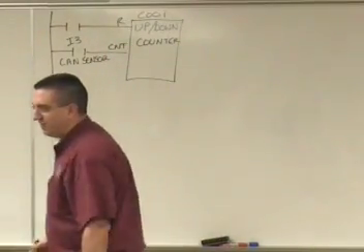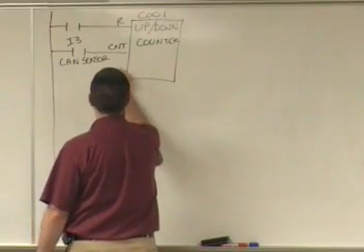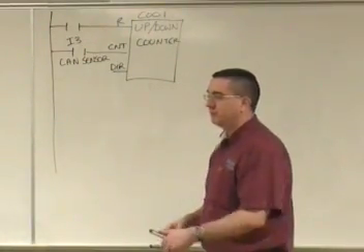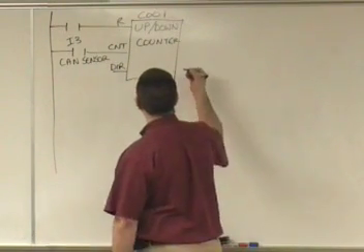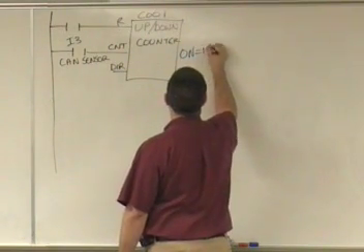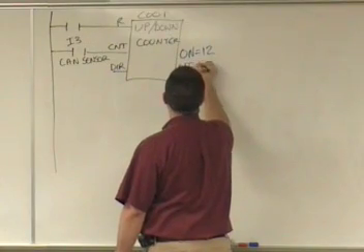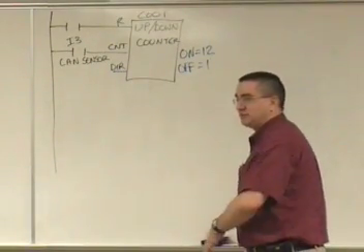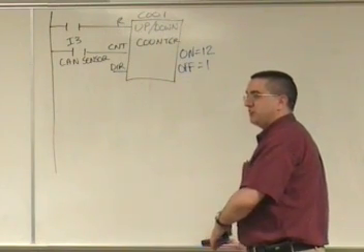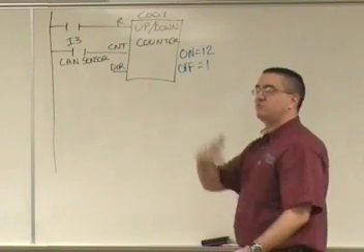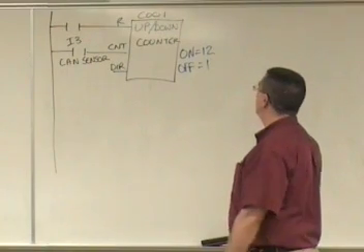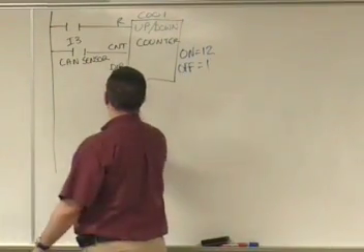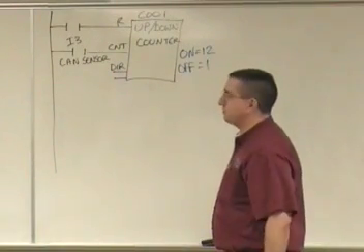That comes into the count pin. And then I know I have a direction pin, but I'm not going to use the direction pin because I'm only going to count from 0 to 12. So over here, I'll say that my on threshold equals 12. My off threshold equals 1. Because all I'm going to do is count to 12, run the packaging machine. When the packaging machine is done running, I'm going to reset it, count to 12, run the packaging machine. And so there's my parameter. We know that our parameter actually goes to a green pin here somewhere, so I drew it in there.